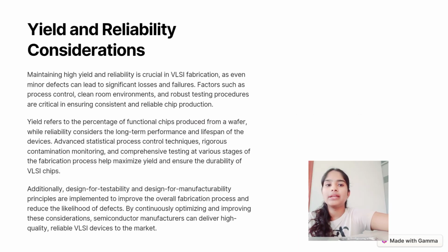Yield and reliability considerations. Maintaining high yield and reliability is crucial in VLSI fabrication, as even minor defects can lead to significant losses and failures. Factors such as process control, clean room environment, and robust testing procedures are critical in ensuring consistent and reliable chip production. Yield refers to the percentage of functional chips produced from the wafer, while reliability considers the long-term performance and lifespan of the devices.